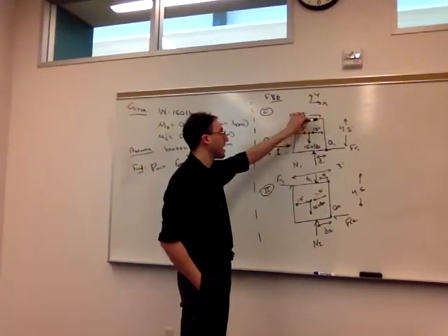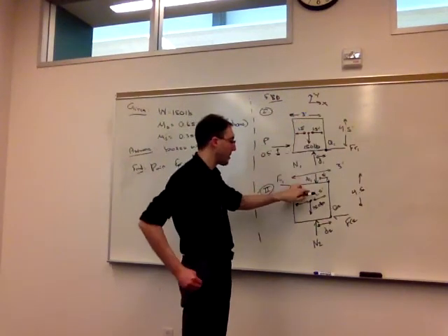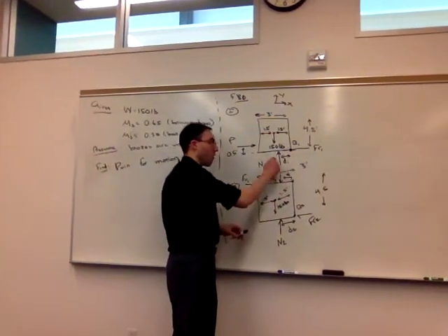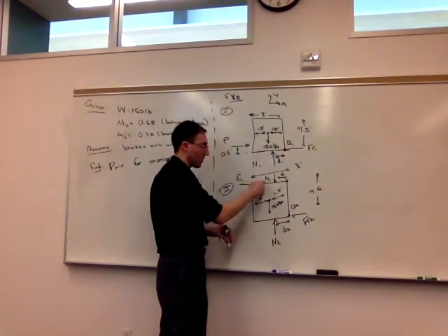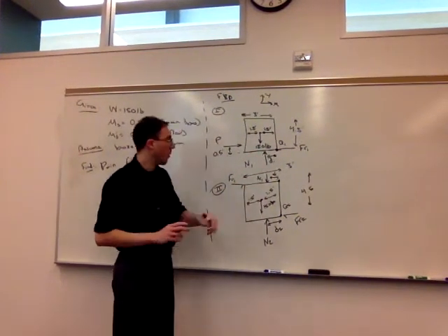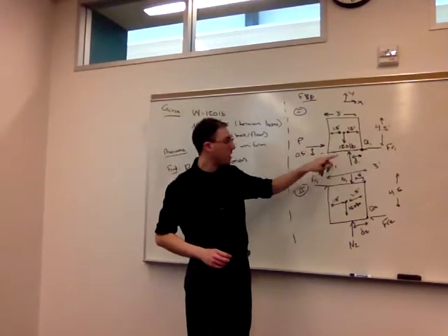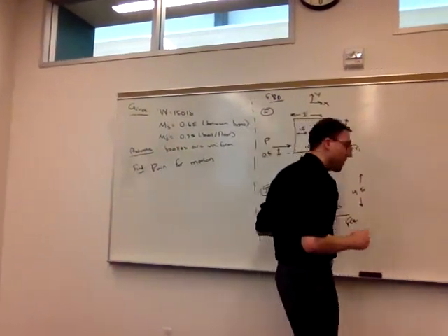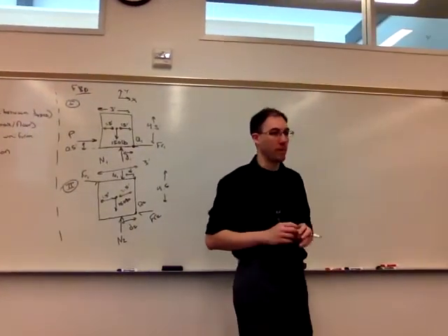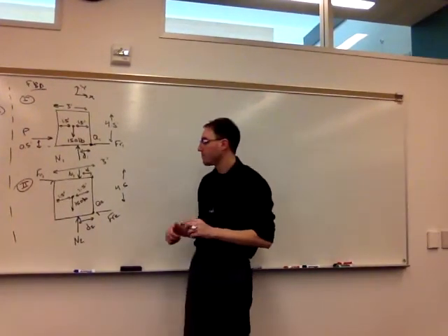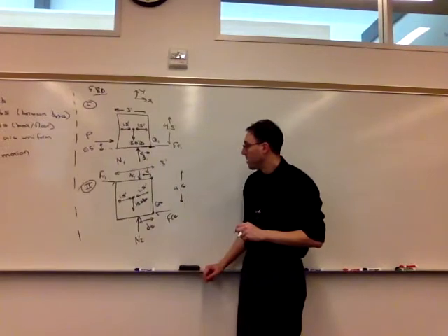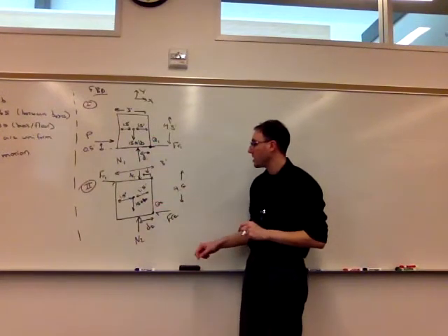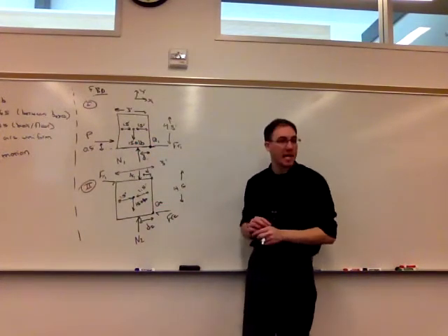This is the gravity acting on the box. It will indirectly be in this picture because the normal force feels the 150. The normal force is also in this picture. So we don't include the 150 directly, but we will see how it transfers through. So the 150 from only this crate would appear in the picture. So these are all of the forces. There's no couples acting on the second crate.